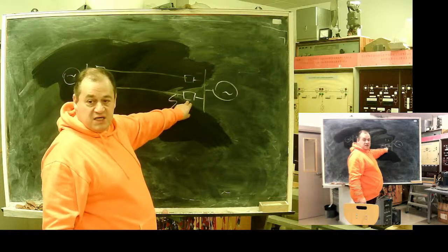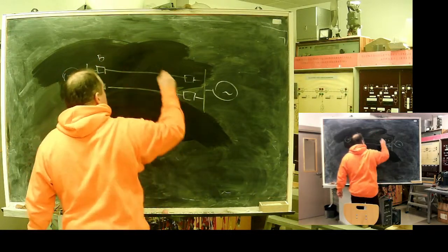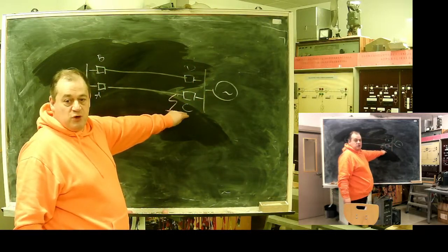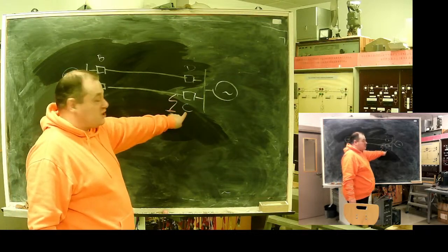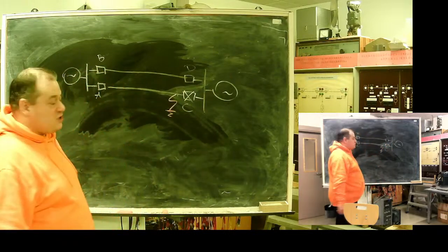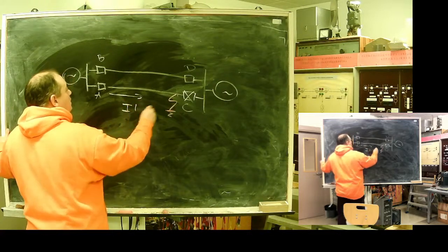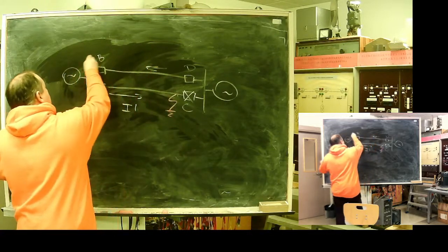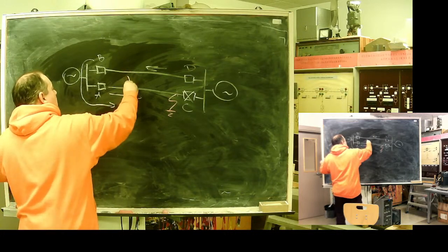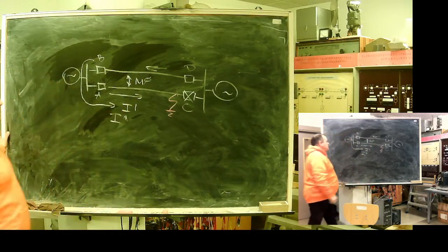For the near protection, let's say A, B, C, D. For protection C, the fault is in the first zone. So this protection trips first. After the switch is disconnected, we will see I1 and I2. Again, here is mutual coupling in zero sequence.